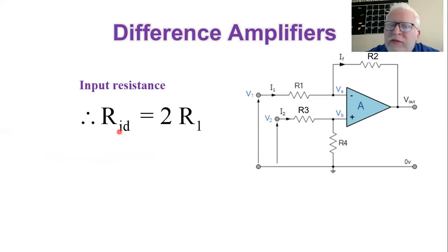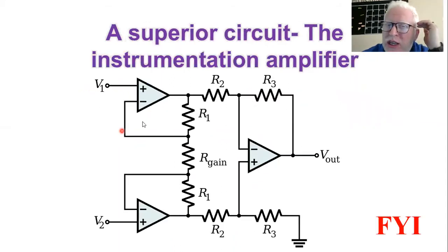Thus, this is a very important point. And in order to avoid it, my dear students, in industry we usually use the isolated differential amplifier. As you can see, this second stage is typically a normal differential amplifier where you have one input to the inverting terminal and the second to the non-inverting terminal.